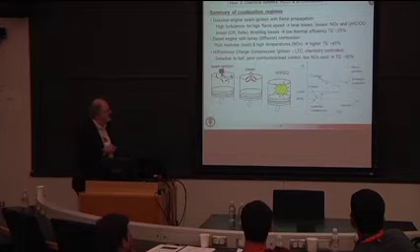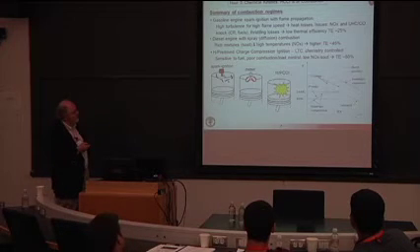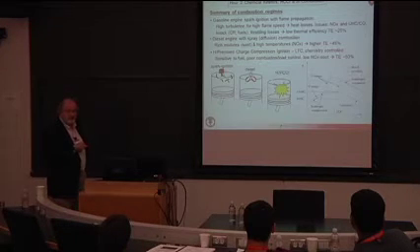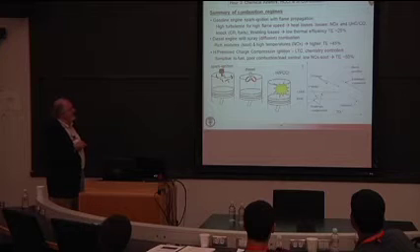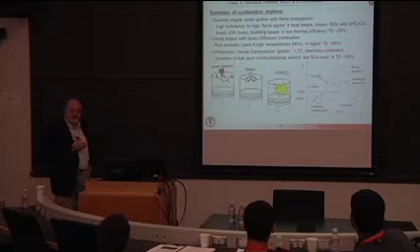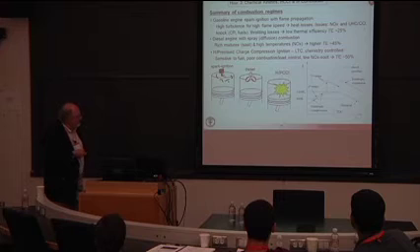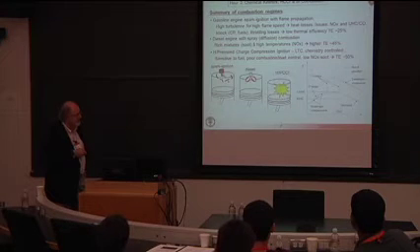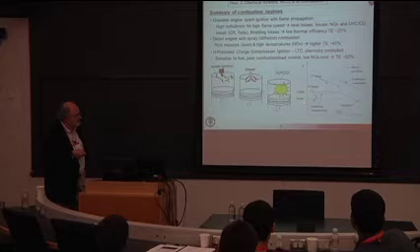Now, if you look at homogeneous charge compression ignition, this is a low temperature combustion strategy. Basically, the combustion is controlled by chemical kinetics. That makes it very sensitive to the fuel that you use. So for example, here I'm showing a plot of in-cylinder temperature versus crank angle. I'm assuming I have a homogeneous mixture here in my combustion chamber, and so I can just plot one temperature here.